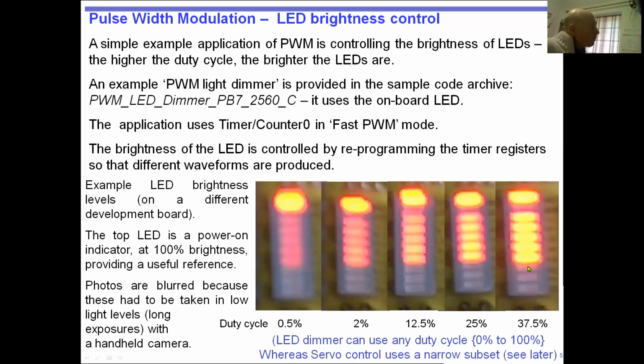This is useful because you can use this for generating effects other than just LEDs on or off. You can have different brightnesses. And if you have a red, green and blue LED, by changing the brightness of each one, you can make multicolor LEDs. But also, you can save power. If you have a battery operated device and you connect an LED, normally you only control the LED brightness by the value of the resistor you choose. But here we can control the brightness, and we can make the LED dimmer. For example, in daylight, we can use dimmer LEDs, and we can therefore save energy.